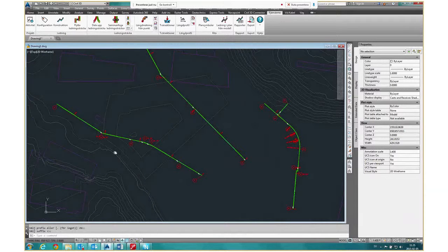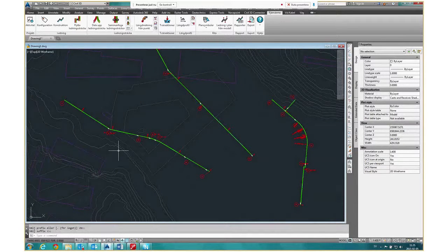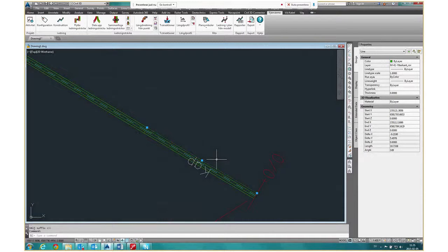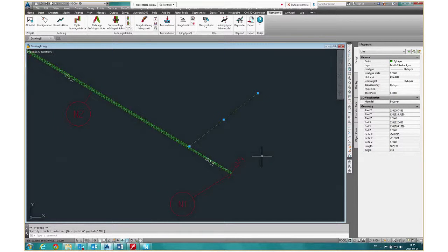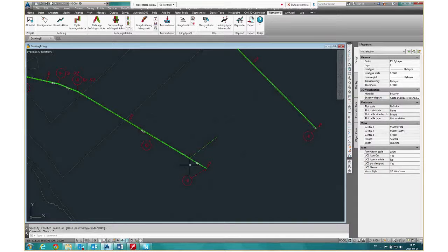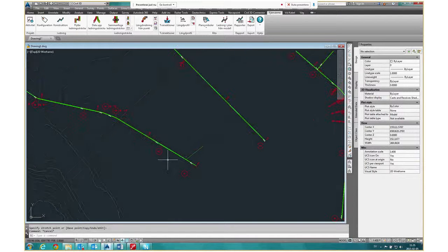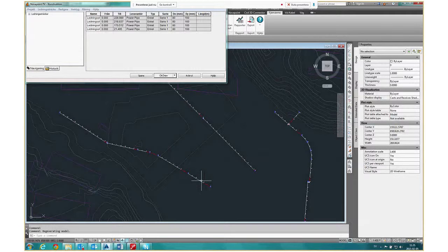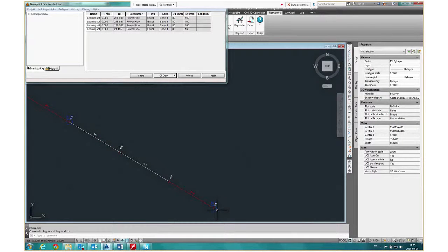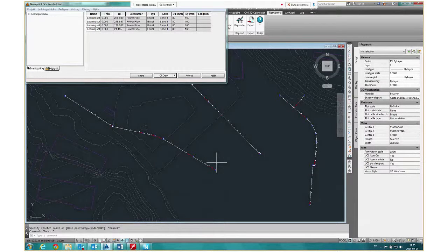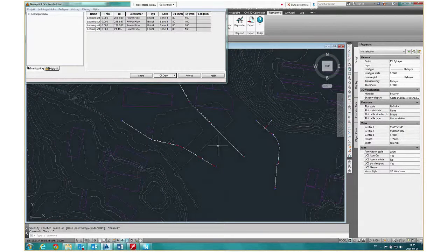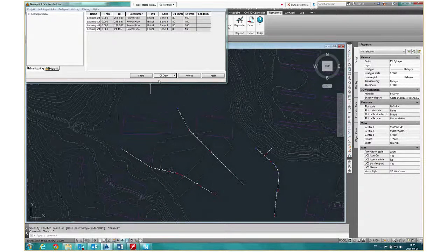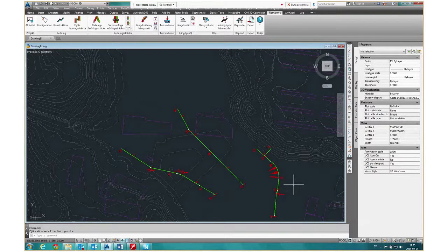What we see here are dead lines that we just draw from our construction. If I move this line over here, it is not projected in Novapoint. If you want to make a change, you have to go back to the construction dialog, and you see the line jumps back. So it's in here we have to move for it to work.